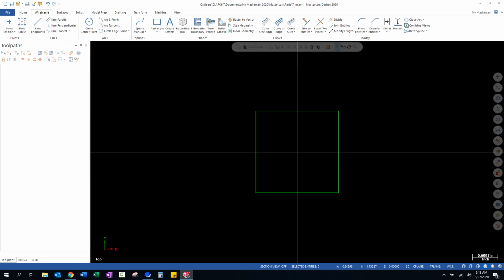And facing is a machining process that takes a cutting tool with a flat surface on the bottom that has cutting edges, and it's going to machine away that surface so that the surface is indeed truly flat. When the material comes to us from a vendor, it's usually extruded or formed in some way, and the surfaces are not necessarily flat. So the CNC machining process will do that. Okay, so we're going to use a milling machine to do this.